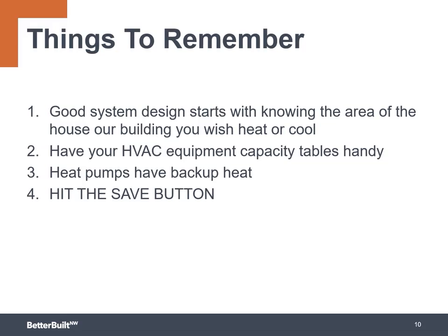And remember that when we're dealing with heat pumps, you don't have to have 100% heat at design temperature. They will have some form of backup heat, so you want to make sure that they're sized to optimize the system performance and comfort, but not necessarily meet all worst case conditions. And of course, always remember to hit the save button between going from tab to tab.